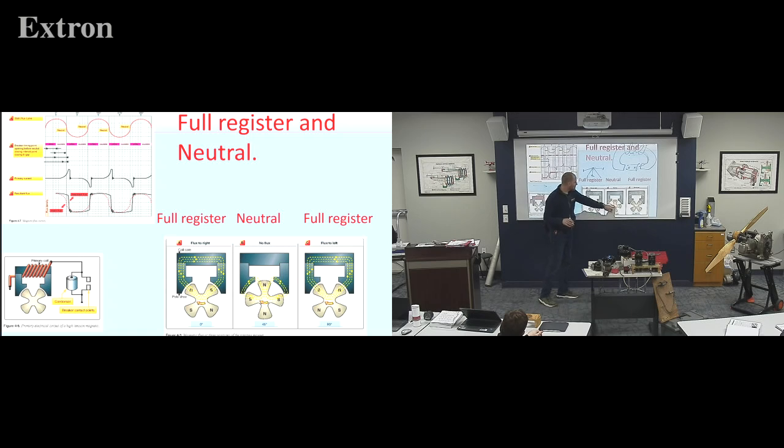So we're actually going to take our spark off when it's very close to that neutral position. And I say very close, we'll deal with why not exactly. But what we're doing is we're changing from, let's say, a positive direction to a negative direction with our voltage, and we're changing the fastest from positive to negative at that point.